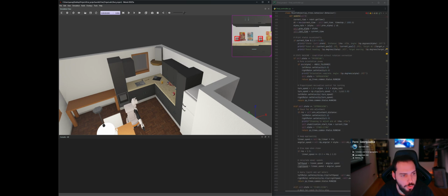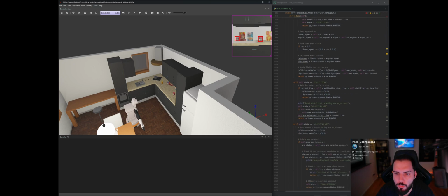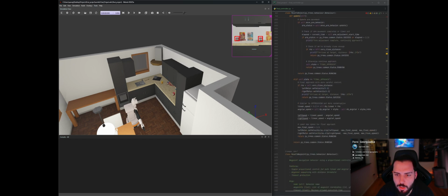Especially in Webots, in an environment like this, you can find that if you press play on the scenario multiple times, 90 out of 100 times it'll work, but then there's 10 times where for whatever reason there's motor and movement oscillation, and it causes the gripping to fail or the arm to be off just a little bit where it's not going to work. So I really wanted to make sure that we slow down once we get really close to the object in order to prevent all of that.